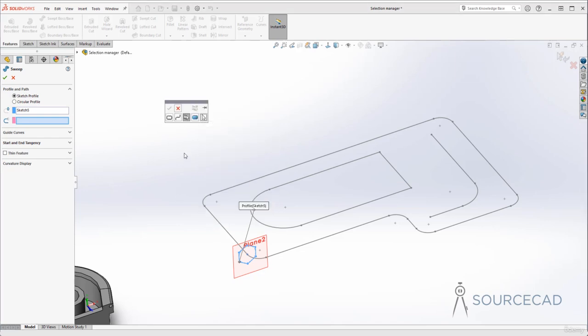That's going to show up, and now we have options like this closed loop. Select this, and now you will be able to select this entire loop with just one single click. So you don't even need to select all of these edges now. It's going to select it all using one single click. Not only that, if you want to select an open loop, then you can select this option and then click on this open loop, and that's going to select the open loop.